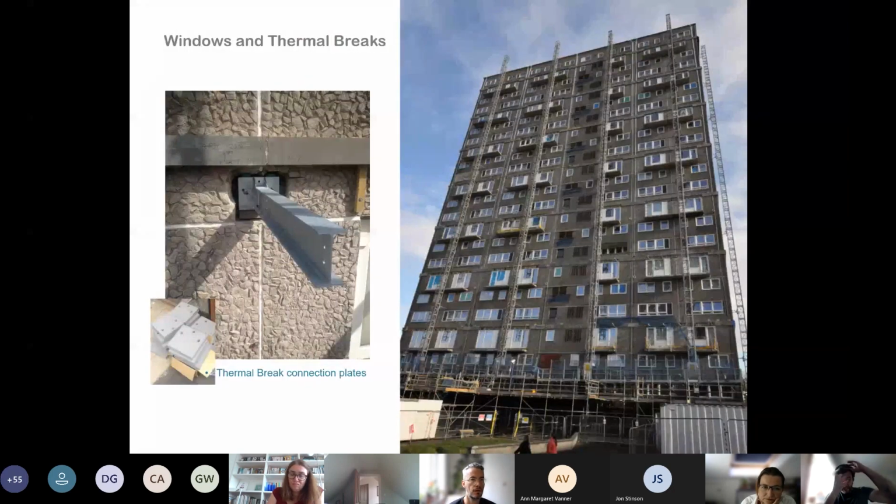During the contract, when putting in these winter gardens, there was a requirement to add more structure in to support the roof canopies, and introducing steel to support the actual structure creates its own complications with thermal bridges. So the outriggers here go directly into the floor slab, but we have isolated the thermal bridge with 50mm structural thermal packers or thermal breaks. But you can see that it creates a bit of a complex junction for air tightness as well. We've had to seal that area up and use the 50mm depth of the actual isolation packer to its benefit for the air tightness strategy.